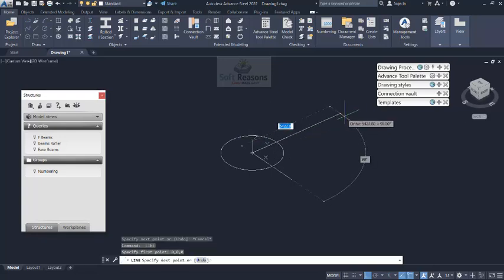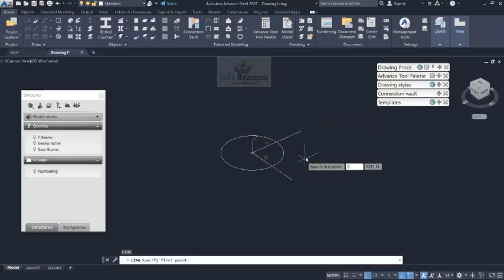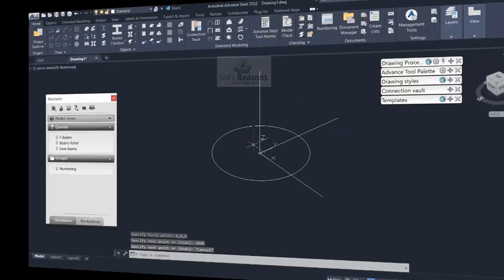Go to the Y direction, you have it to be 3000. This is how I normally set my UCS. I normally customize my UCS just like this, and then do line again 0, 0, 0, Enter. I go up, and make it 3000 millimeters upward. I'm trying to set my UCS, customize it.